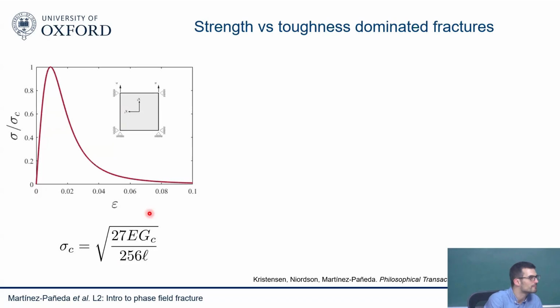Yeah. This element size should be small in all 3 directions with the L? Yeah, if you don't know where your crack is, that's a good question. If you don't know where your crack is, then you need to put your mesh fine enough. So what this has led to is people use either adaptive mesh refinement, so they will just have a coarse mesh, but then they have some criteria to make the mesh smaller as the crack grows. Or what people will do is run one simulation with a coarse mesh, see more or less where the crack likes to go, then refine that area, run another simulation, keep refining. So you do 2-3 calculations just to know where the crack goes.